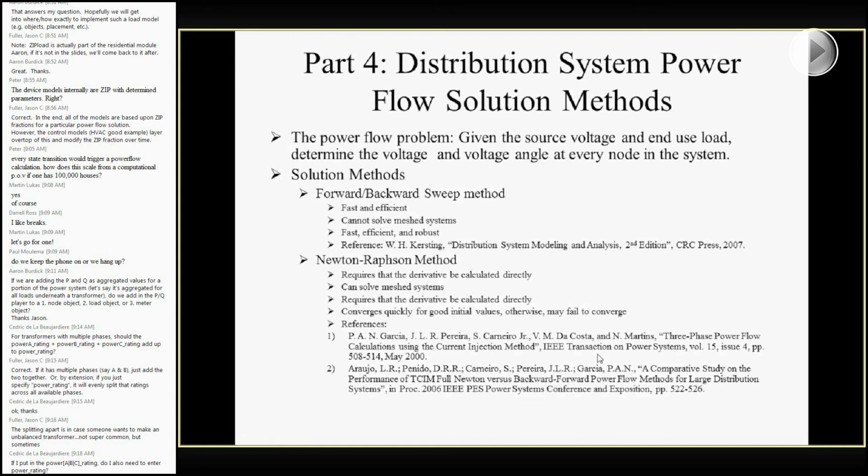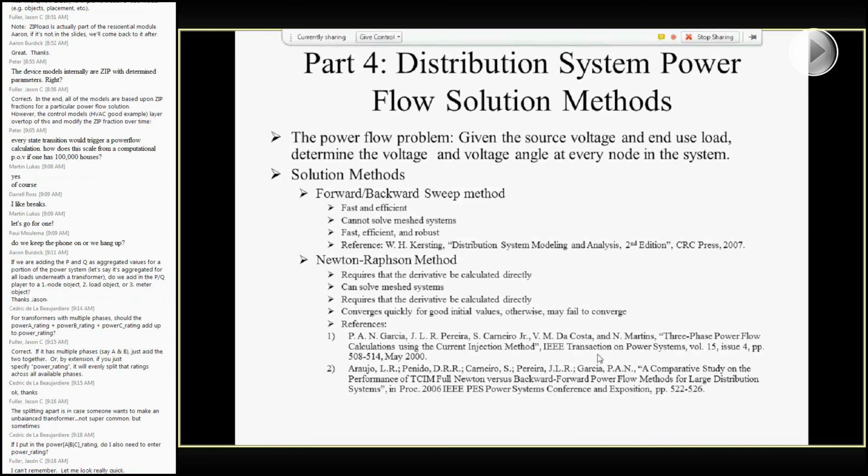The basic way to look at the two Powerflow solvers is if it's a completely radial system and you want a fairly quick solution, forward-backward sweep works well. If there's any chance that there's a mesh system, or if you want to do any reliability concerns, the Newton-Raphson system is the one you want to use to solve all of your power flows.